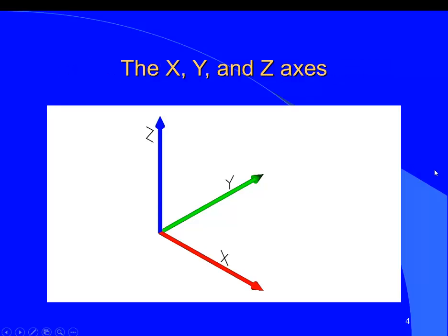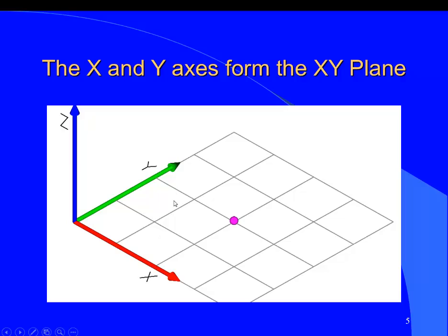So there are our principal planes, our 6 views. Here's our X, Y, and Z axes. Now we are going to be just drawing in 2D, representing the 3D drawings. Typically the XY represents the flat plane, so you're looking down on it like the top of your desk, for example. So if I have a point and I've located it in the X and Y plane, I haven't fully located it because I don't know the up and down location of it.